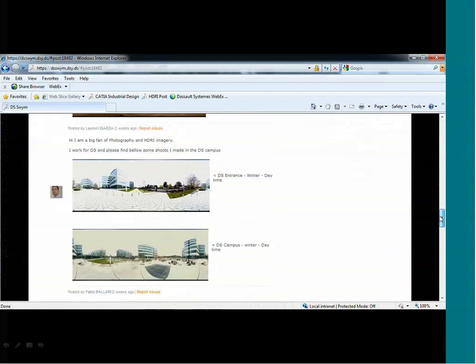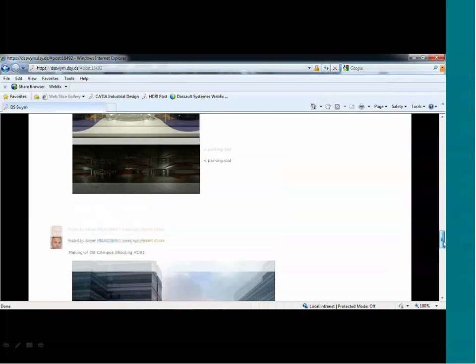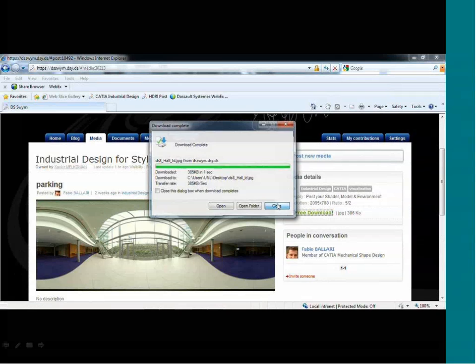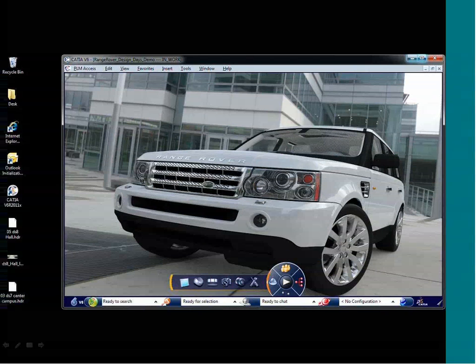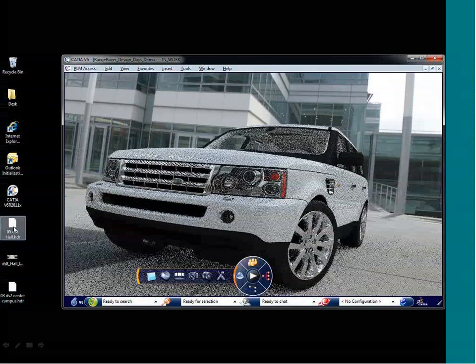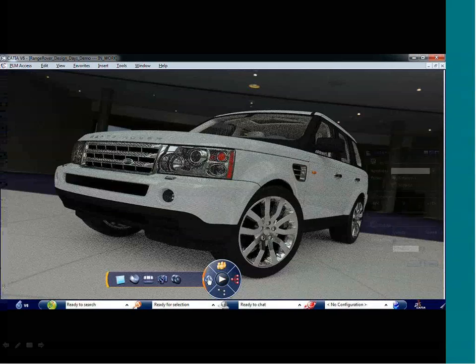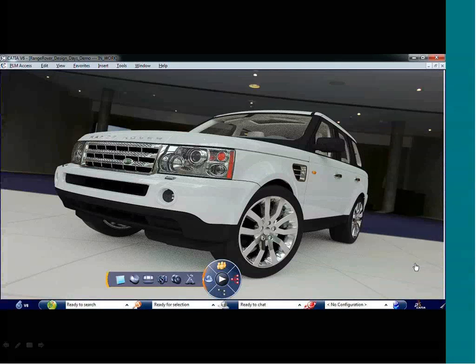It's also based, in terms of lighting, on HDRI imagery. So at any time you can bring any HDR image that you have to visualize your object within CATIA in another environment. So you have multiple options. You have a library of HDRI within the solution, or you can simply drag and drop your new HDR and visualize your product in your environment, image based on HDRI.